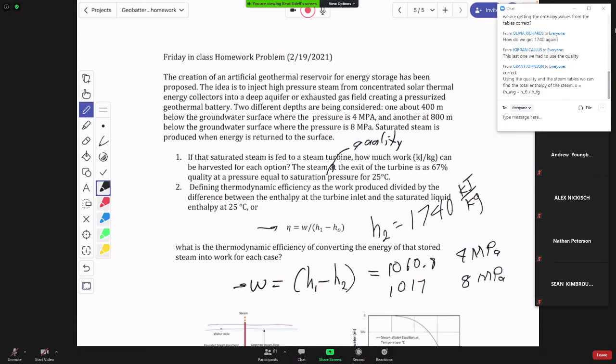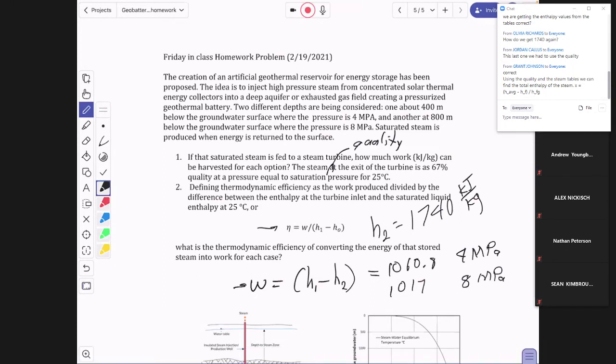The place that it is referenced to always is going to be the base case of where the whole system started. Remember in my figure that there is that water storage tank: steam comes out and condenses and gets stored in the tank, and then that gets fed to the steam generator. So the enthalpy of that fluid, that's the enthalpy of saturated water at 22 or 25 degrees. Okay, it always goes back to the base case.